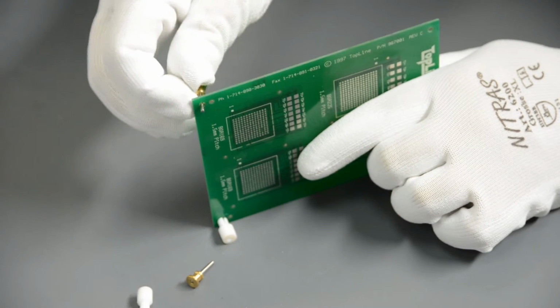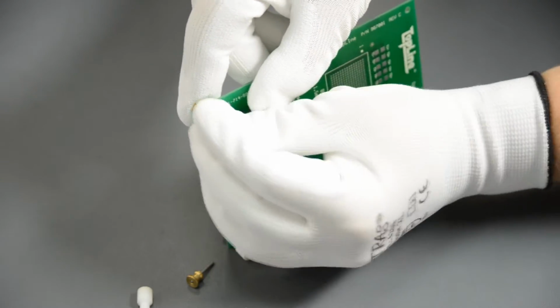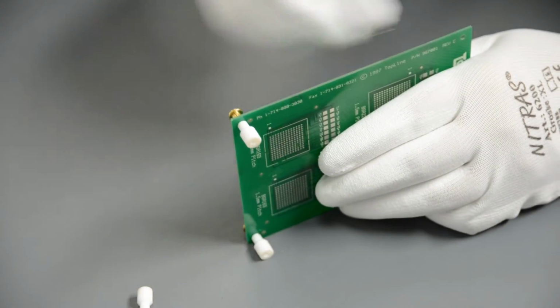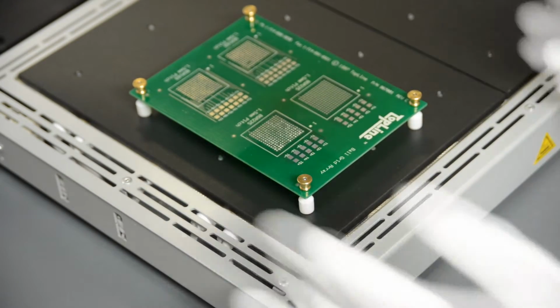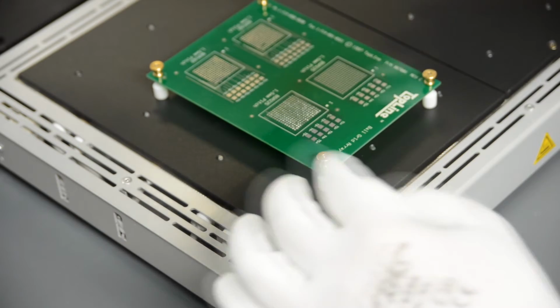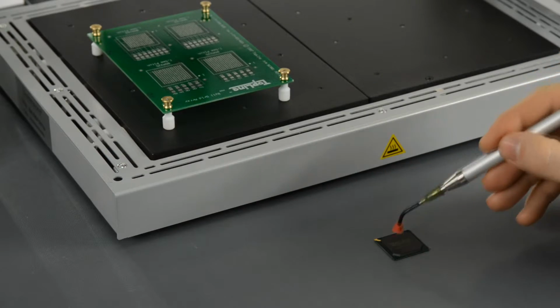Place the board you will process on the bottom heater plate with an optimal gap. Use the supplied fluoroplastic racks for that. Try to place the board in the center of the heating plate, which lets you keep equal temperature conditions across the board body and will prevent, or at least minimize, deformation.